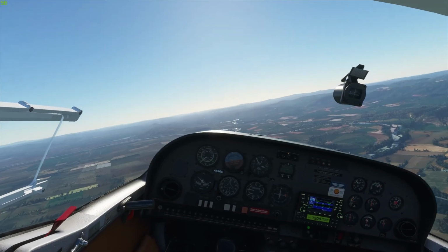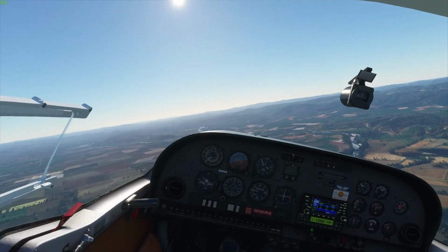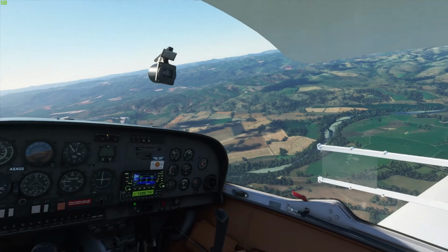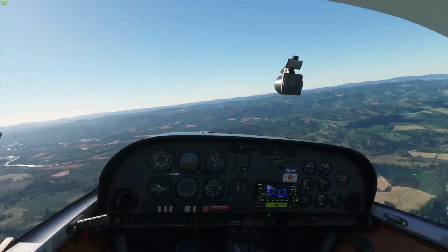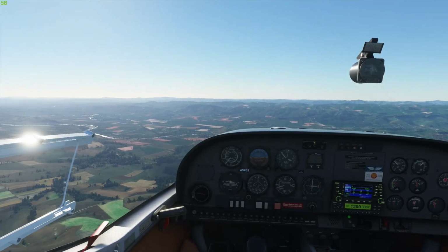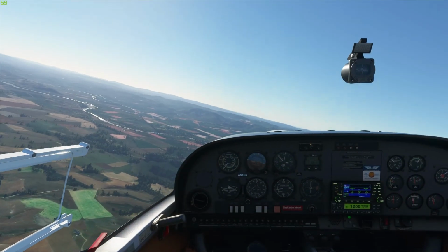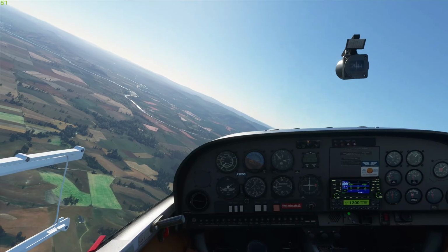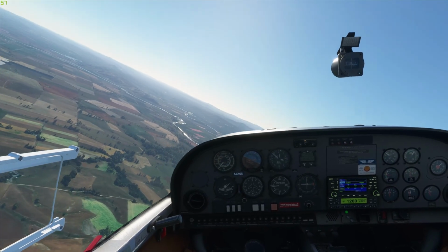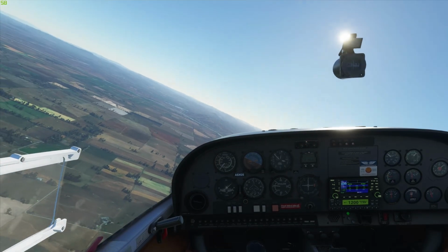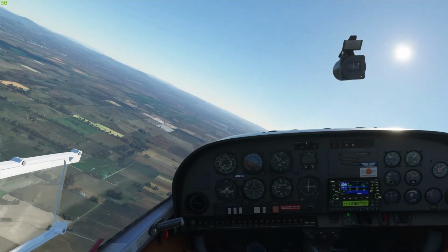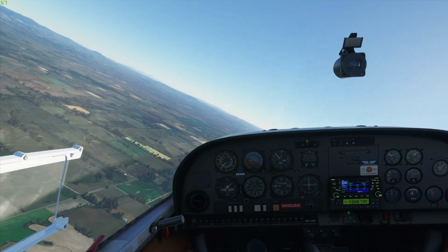Alright, so that's just coming through about 270 degrees of turn. Bring it back around to the left. We're all clear. And just holding the nose on the horizon. Got a 30 degree angle of bank this time, and the speed is pretty steady, around 100 knots now.